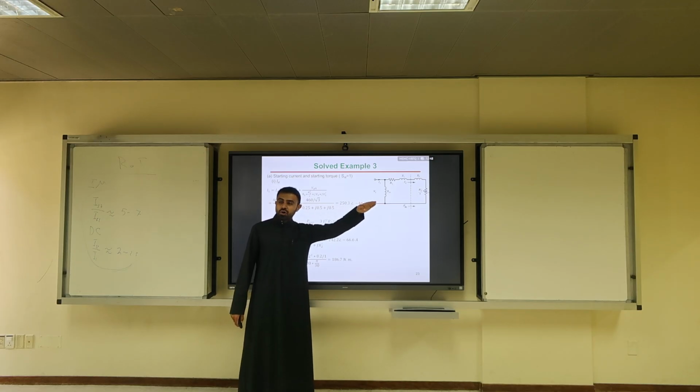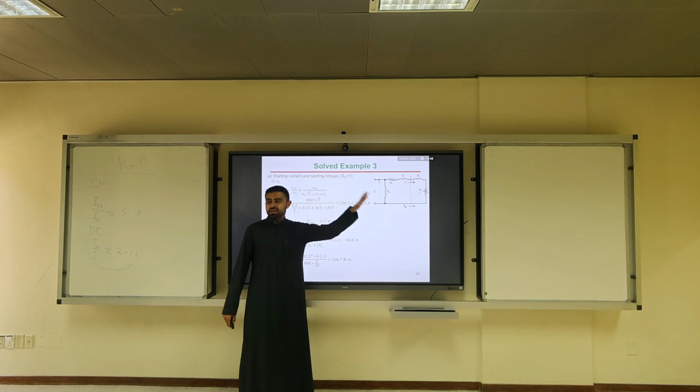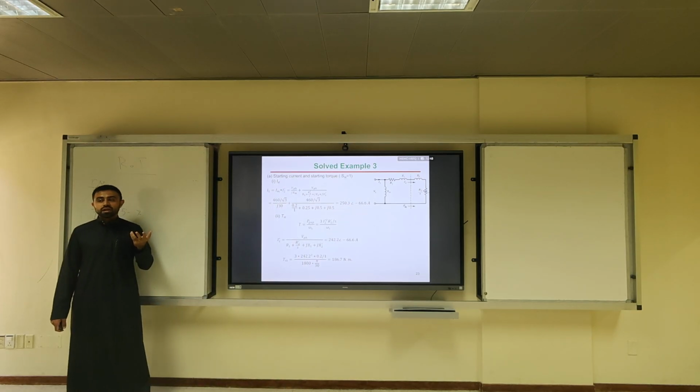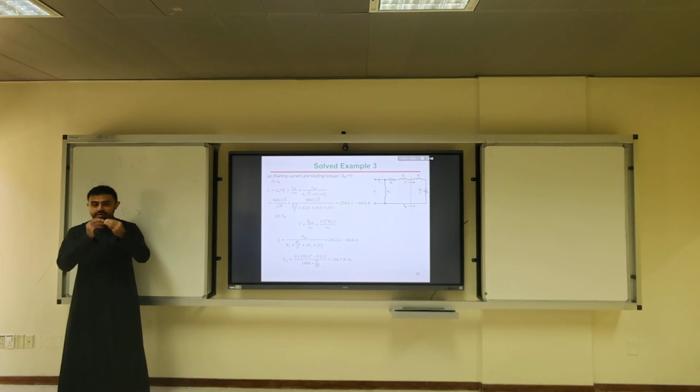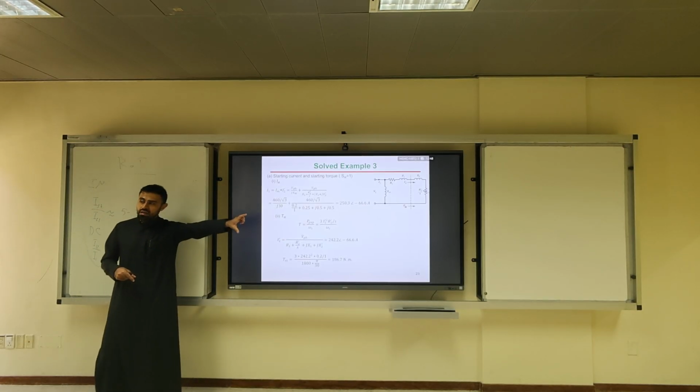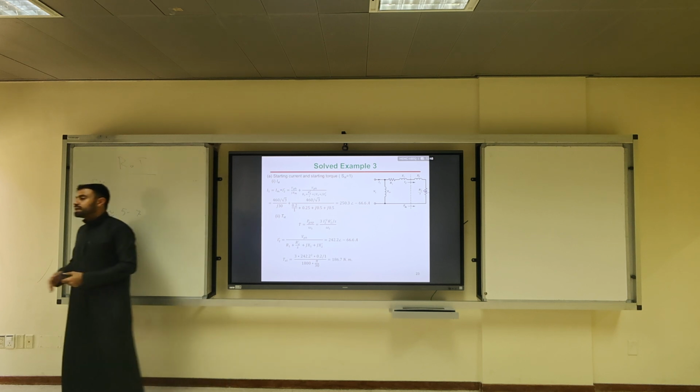When we reach the full load, we have very nice power factor lagging. For the synchronous machine, what is the power factor? It depends on the field and on the armature current. So you can see the power factor in a synchronous machine spans from lagging to leading, but for an induction machine, it starts at low lagging up until it reaches high lagging at full load. It will never ever be leading.